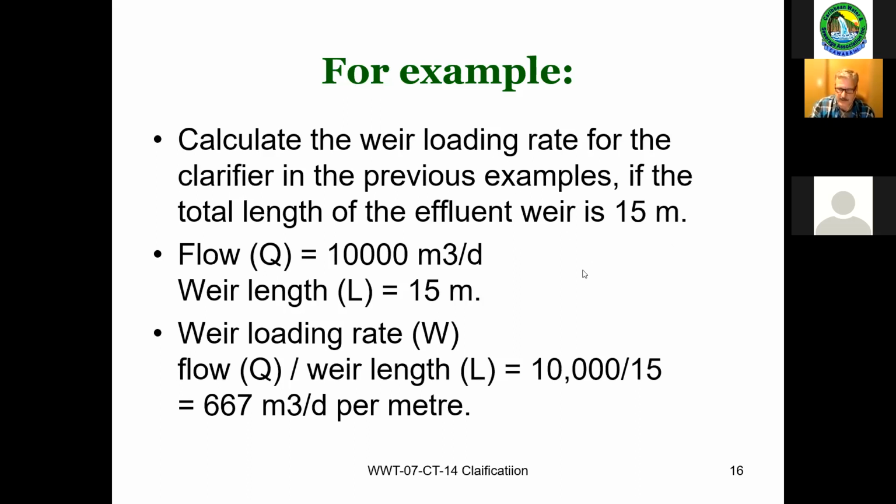Again, you do have calculation sheets provided through the exam, but weir loading rate is basically the flow divided by the length of weir. If it's a rectangular tank, it's very easy to figure out the length of that weir with a measurement. Circular tank, same thing. You just need to do the calculations to turn that circle into a length that you can divide the flow by.